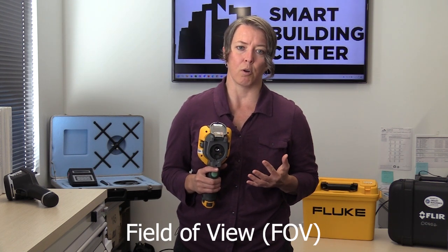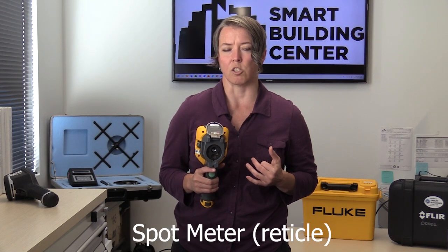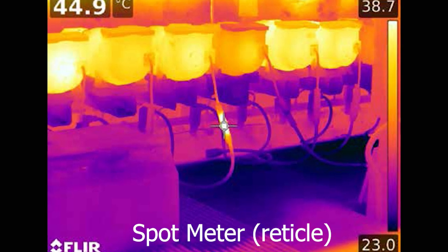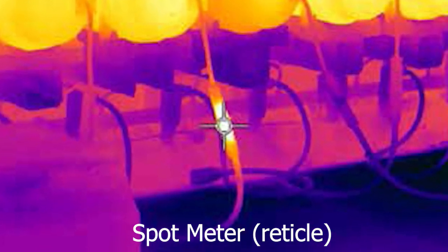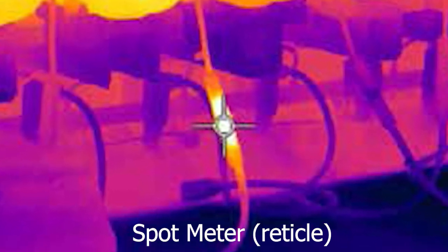And the second component to this is the spot meter, also known as the reticle. And so this is like the little crosshairs in your image. That is where you are taking the measurement. And so you want to make sure that the target of your measurement overfills that spot meter or reticle. That way you are covering enough pixels for that measurement to be accurate.